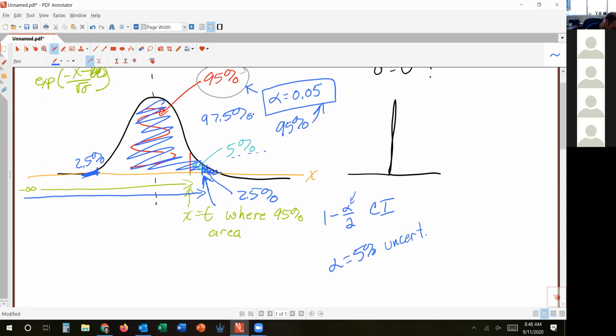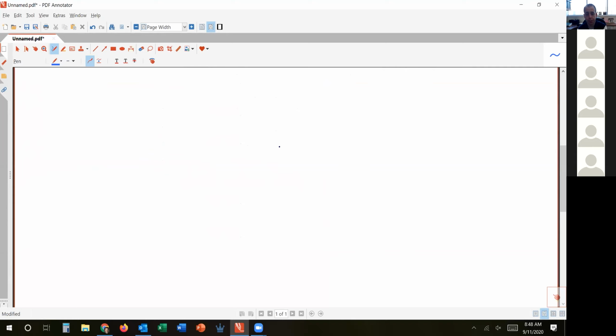It's used all the time in engineering for process control, because S should not change as long as my system doesn't change. I can use that to make sure that my system is staying in spec. So I've got these plants or these processes that have been running forever, and I'm measuring temperatures or pressures or concentrations. And I know, because I've taken them for so long, what it should be at. So let's say in hour 1, I take a reading and it's right here. The next hour, I might be right here.